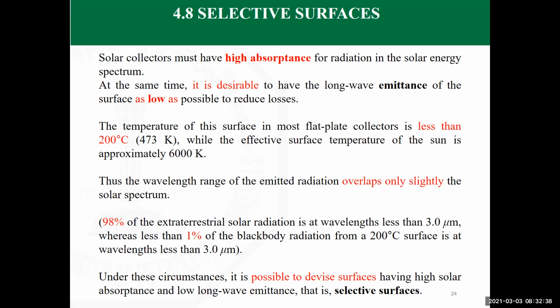And in many cases, this receiver is covered with glazing or a glass. Sometimes it does not, but most of the collectors that we know that we are using are covered with glasses. Those that are not covered with glasses are the ones that can be used for heating water in swimming pools, for example, where you don't expect to heat it to a very high temperature. But if you are looking for considerably higher temperature, 70, 80, even 60 degrees centigrade, then normally they are covered